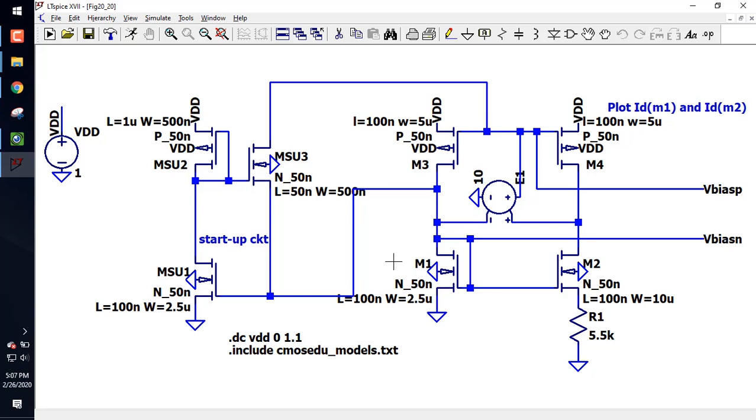If I get on the loudspeaker, or I get on the microphone here, and I say hello, and it comes back through the speakers, and it hits this louder than my hello voice, then it gets amplified again and comes back even louder than that, and you get that screeching noise, right? However, if when I talk, it comes back and it's quieter, then it gets amplified, but since it's at 0.9 of my voice, it amplifies a little lower. Then it comes back at 0.8, gets amplified a little lower, then it's 0.7, gets amplified, and it dies out and it stays stable. I don't get the screeching.